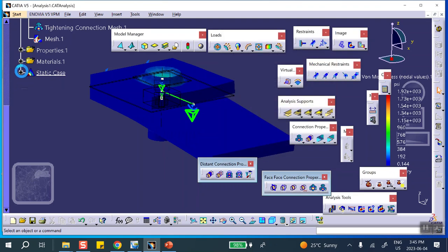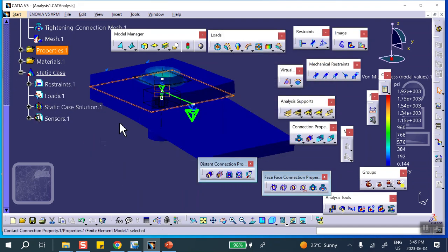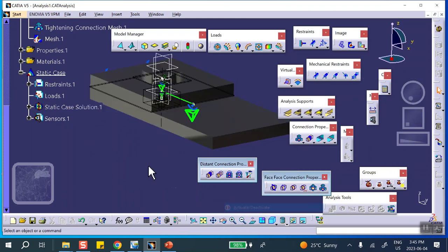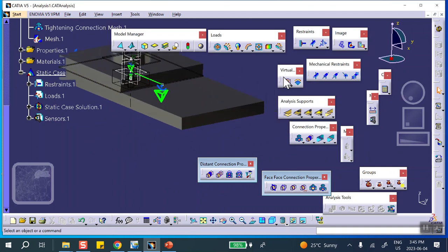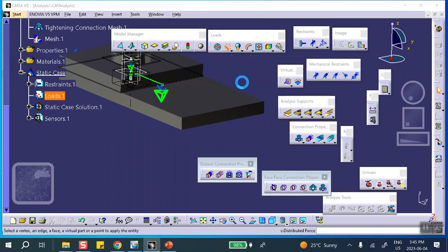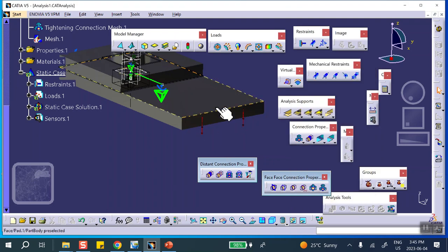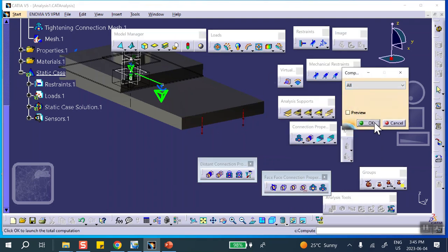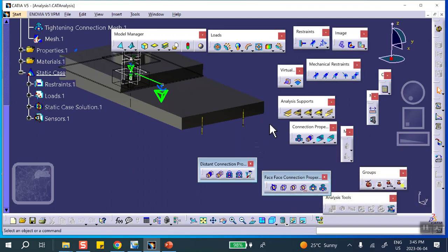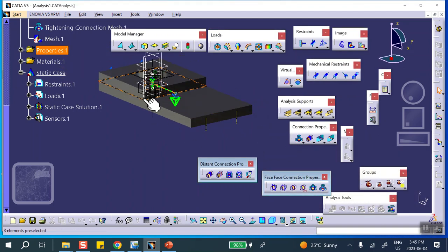All right. Deactivate this plot, or either you can put it here. Deactivate it. Okay. Now we're going to put a 100-pound force at this face, because remember that was part of the problem. 100 pounds, I believe. Yep. So you apply a force on that face, downward, minus 100 pounds. So not only do you tighten that bolt, but you are also pressing this thing down. So now we're going to run it, and it's going to take both the load and this thing into account.